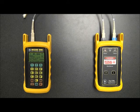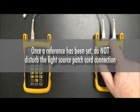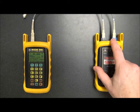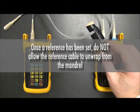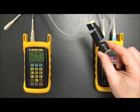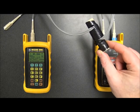However, before we do that, I want to cover a couple key issues regarding once you've set a reference with the light source. The first thing is you do not want to disconnect either of these connections once you've set a reference. If you happen to disconnect these cables, they will have to be re-zeroed. The second thing is to not let the mandrel wrap come undone at all. This will also change your reference. If that happens, then you will also have to go through and set your references again.